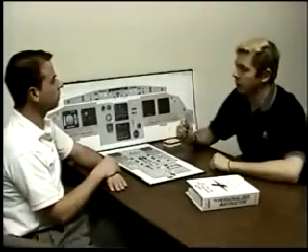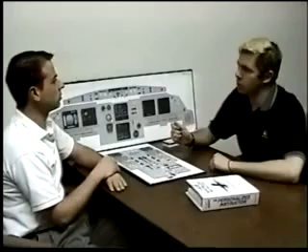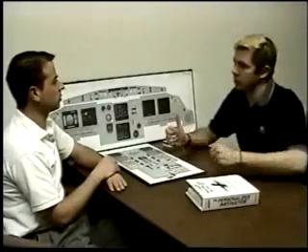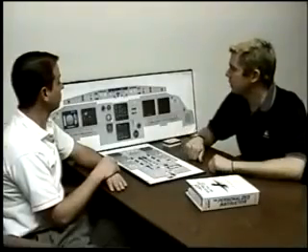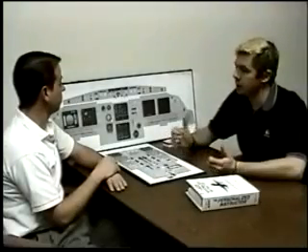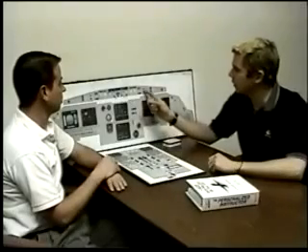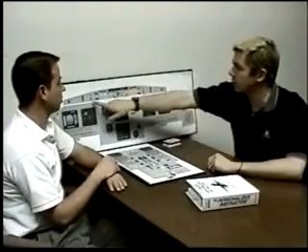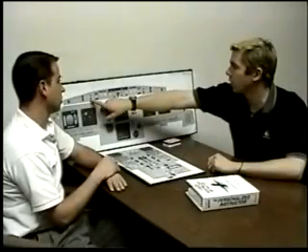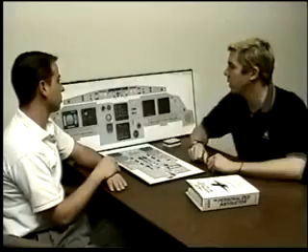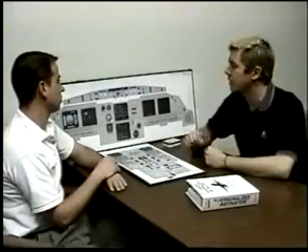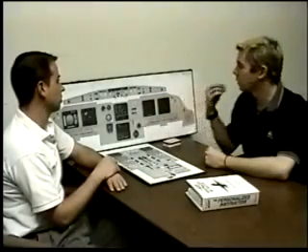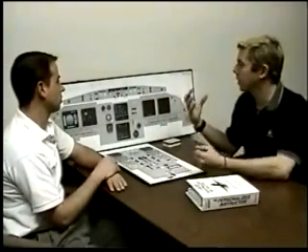If I press and hold it, though, for approximately 30 seconds, then it will latch out the captain's. In other words, I can let go of it after that, and the captain's stick will still be locked out. The captain can get his control back by either of us pressing our buttons. As far as the lights go up here, whenever I get priority, the guy on the other side is going to get a red light. And then if he subsequently moved his stick, I would see a green FO in front of me indicating, hey, first officer, you have control of the aircraft, but the other guy is still moving his stick.